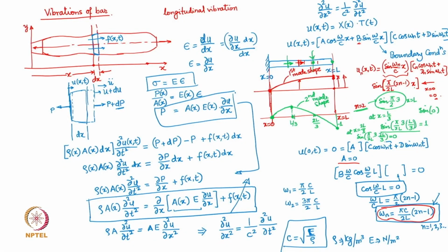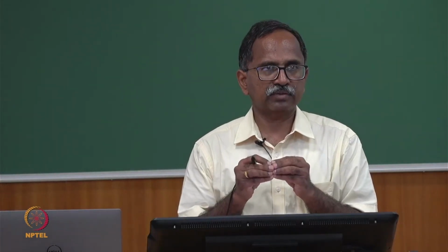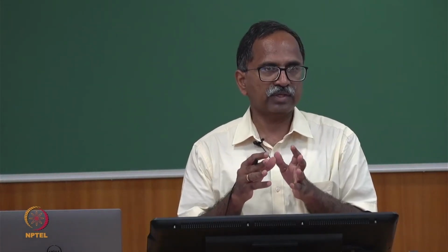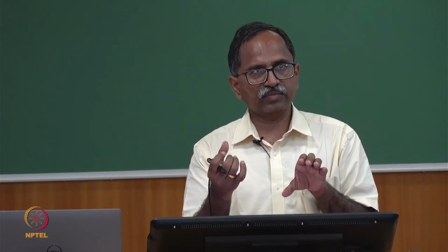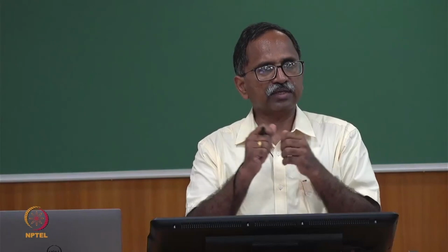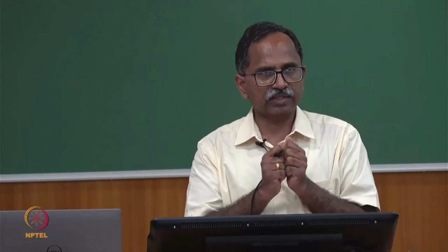Why? Because that location of the bar will see no vibratory motion or significant vibratory motion. If I want to clamp anything there, I would have a preferred location to clamp at the node position, because at all other positions there would be stretching and compression and continuous vibratory motion taking place.